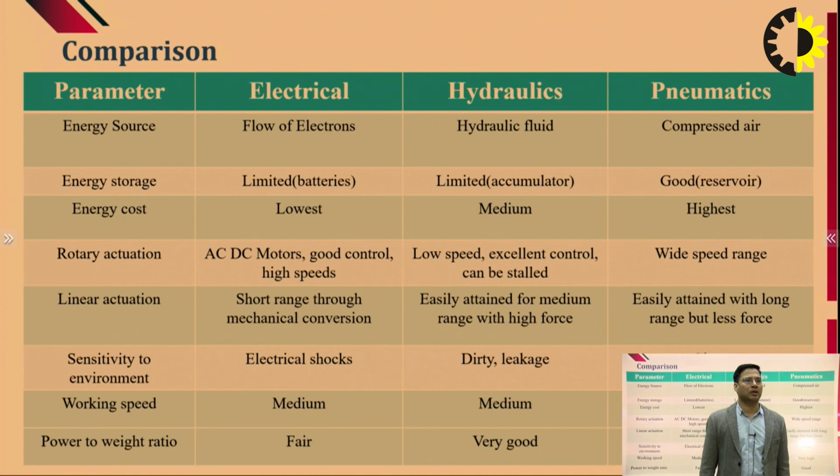If we talk about parameters related to storage, in electrical we have batteries as devices wherein we can store the energy, but in hydraulics we have a limited source of storage, that is accumulators, which can perform the operation for a number of cycles only. But in pneumatics you can have a reservoir in the name of a tank, which actually offers good storage performance of any energy.